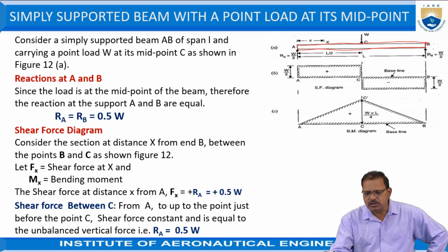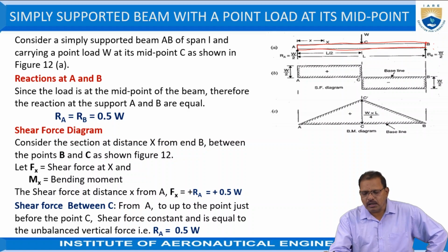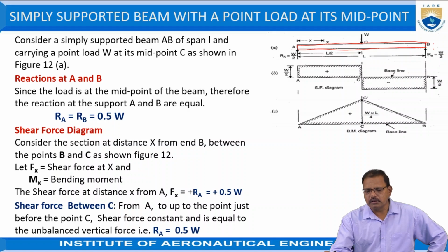Now, in the previous discussions, the reactions offered by the supports are also treated as the loads which are acting on the beam. And so, while drawing the shear force as well as the bend moment diagrams, we have to determine the magnitude of the reaction force at A and B. Since the beam is under equilibrium by the action of the reactions at A and B as well as the W at its center,